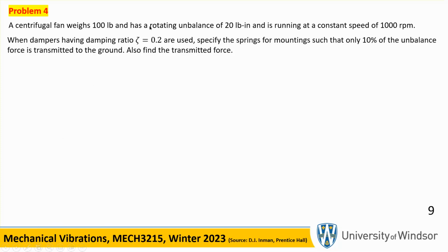Now, because it's an unbalance here, you have to give meaningful interpretation to F naught, and that's going to be the mass times omega squared times eccentricity. Okay? Now, eccentricity is not given to us by itself, okay? But we're given the product of M by E by G. But of course, you divide it by G, you get the product of M by E. But anyway, let's go ahead and find out what we know.